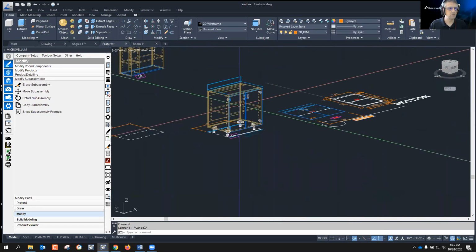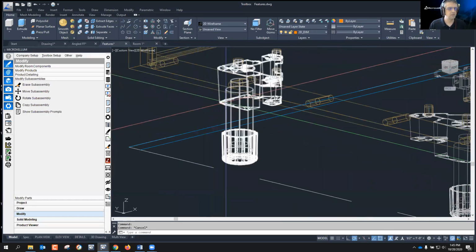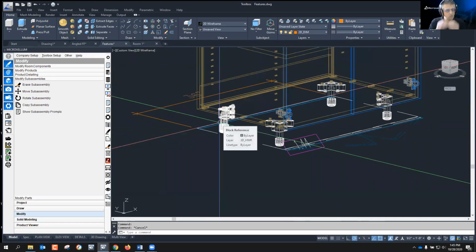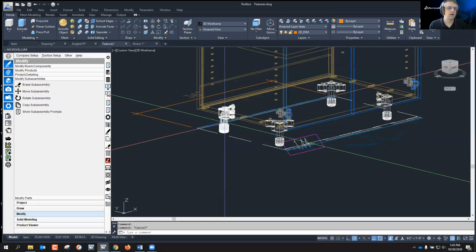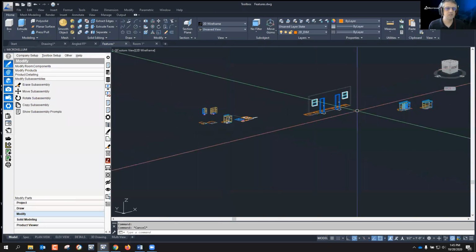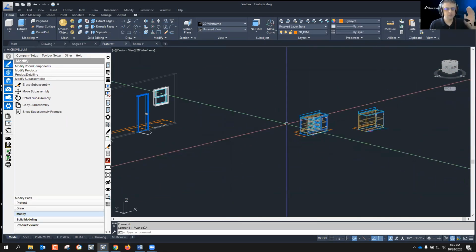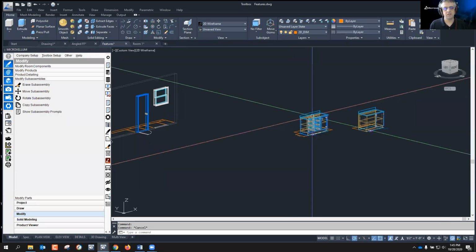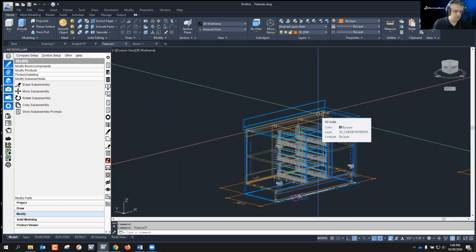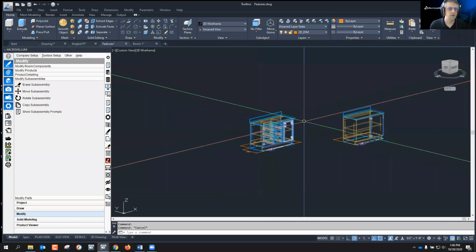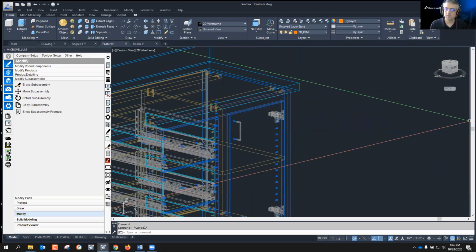The other culprit was, I don't know if it was this one, that leg leveler from earlier. If you zoom in on it, there's just so much geometry going on. It just seemed to really affect performance. So we've been going through and purging out what we can, what we see. We made a utility that went through all the blocks and kind of cleaned them out, to make sure there was no unnecessary garbage in there. We did a purge command. We did an audit. There are things inside of a DWG that you don't need in there, right? Kind of put your blocks on a diet.